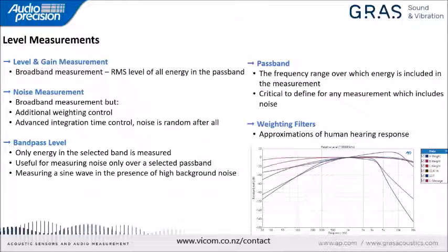But the noise was attenuated with an A weighting curve, which attenuates low frequency sounds and very high frequency sounds, and actually has a little gain in the mid band because our hearing is actually sort of tuned for the center of sound in human speech. And that's an approximation, a way to provide a score, if you will, for noise that approximates how humans would perceive that loudness.